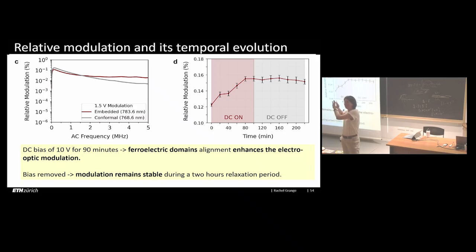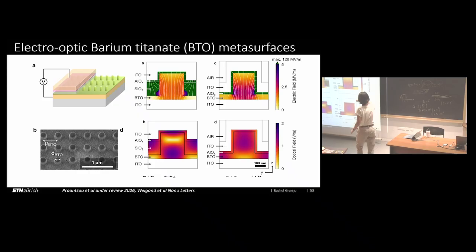Here it's in a material that is totally polycrystalline, but we can align the domains a bit so that we enhance the electro-optic modulation also by applying a higher field inside our system. You see here the advantage of this kind of design where we can control where we put the electrodes: the electrode spacing here is very small.